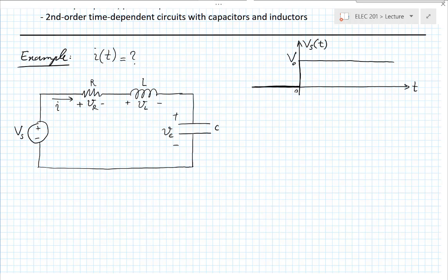Of course, you also have the KCL, which really, at each node, if you write down the KCL, which we have done before many times, you will see that in this case, the currents are the same in all those three elements. And so that's why I just had chosen that one current. So if you write then the element relationships for each of these three, you will have ways of relating VR, VL, and VC, in that they will all be written in terms of I. And then by replacing things into your KVL, you should be able to get a differential equation for I. So try for another minute or so, and then I'll write it down.